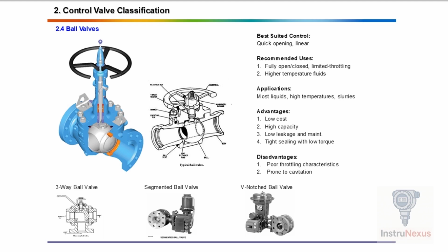When it comes to advantages, ball valves stand out for 1. Their low cost, especially in standard sizes. 2. High flow capacity with minimal pressure drop. 3. Low leakage and low maintenance requirements. 4. And a tight seal with low operating torque, making them easy to actuate.